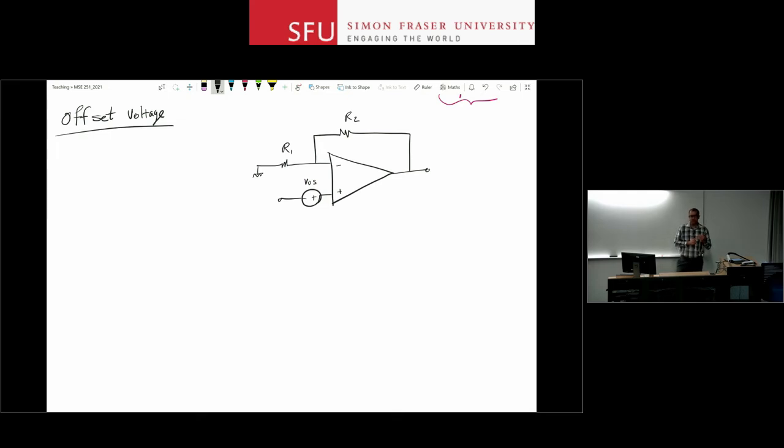And it's a DC problem. Once it is there, it is there. You're going to measure that DC voltage forever. The way to deal with it is, in some cases, the designers of these circuits let you play with the biasing of the circuit a little bit. So you pass a little bit of extra current in this branch or the other branch, and you usually have access to the biasing network through 3 inputs. By playing with the biasing, which is again a DC performance issue, you can monitor the output and make sure the output voltage drops to 0. So you manually set the offset to 0.